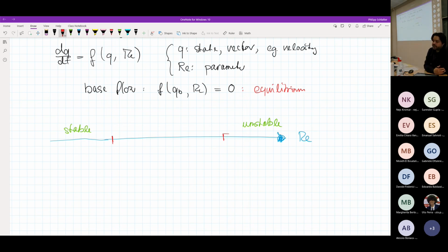Actually, in traditional stability analysis, there are essentially two different critical Reynolds numbers that you have on this way. We have one Reynolds number here, which we usually call Re C, the critical Reynolds number, and that would be the Reynolds number above which everything is unstable. So everything would grow, and therefore we also write an additional word: unconditionally unstable. This intermediate region between what I would also call unconditionally stable is, of course, something that is conditionally stable.